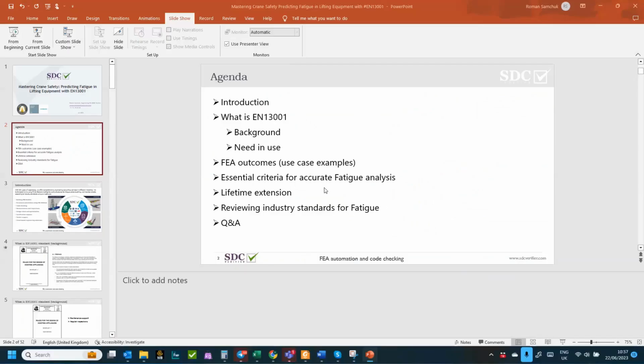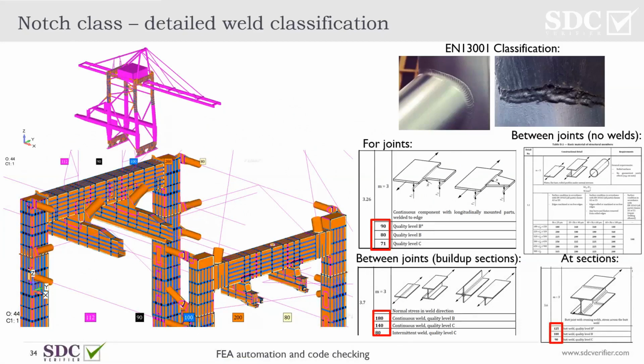In this example, if I have a very strict transition like this, so basically a connection at a right angle, this is apparently a stress concentration point. Your model, if you do the general stress analysis, is already going to show a relatively higher stress level here.